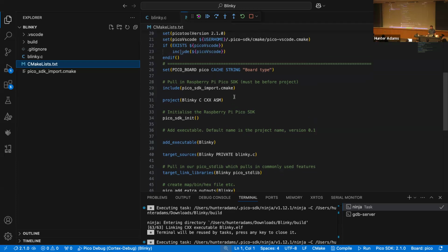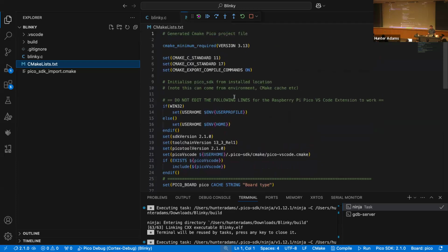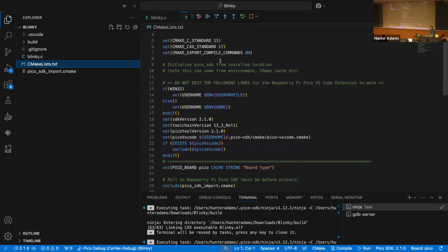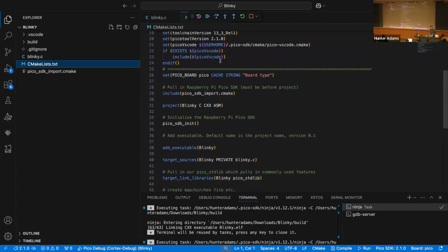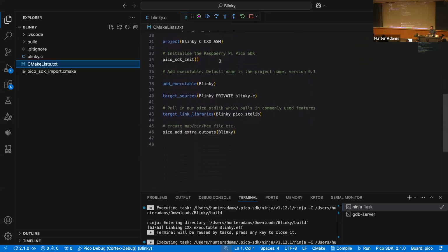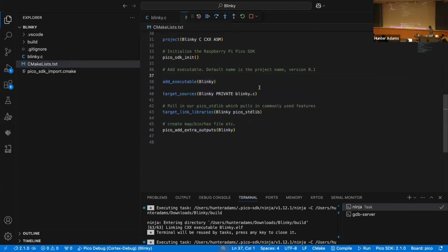All that I wanted to mention about this is when you import one of these programs into this VS Code environment, most of the stuff in this CMakeLists gets automatically populated. The stuff that you will likely have to pay attention to is everything from here down for any one of these projects. And I wanted to just talk through this a little bit. So in every one of these projects that you download, there will be a line in your CMake list called add_executable. That is essentially us just telling the compiler what to call this project we're about to compile.